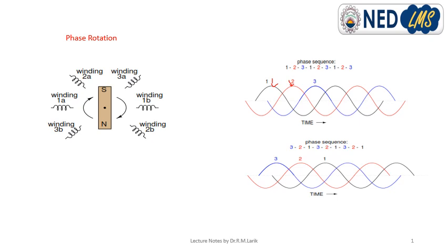The magnet passes by each pole pair at different positions in the rotational movement of the shaft. So the rotational movement changes every time and the angle degrees change every time. Where we decide to place the windings will dictate the amount of phase shift between the windings' AC voltage waveforms. If we make winding 1 our reference voltage source for phase angle 0 degree, then winding 2 will have a phase angle of minus 120, or 120 degrees lagging, or 240 leading.